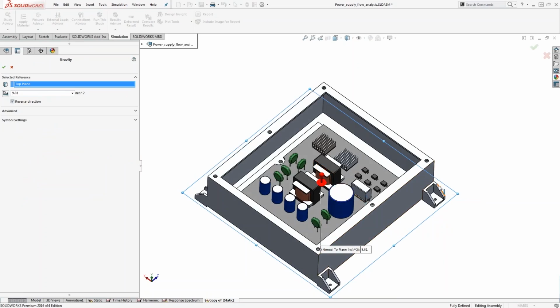So what we can account for here is just the dead load, or the load due to just gravity. But in the case where we're trying to fulfill that specific standard that was applied, where it's in the horizontal direction and should be amplified by whatever was based on that table, we can turn on these advanced settings where we can add a multi-directional gravity load.